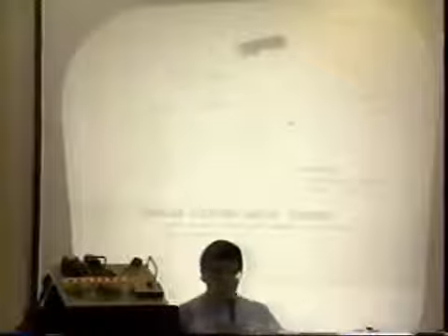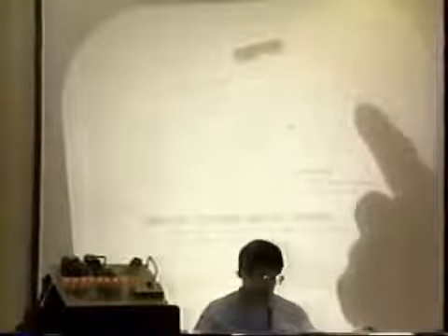Now, why stepping motor? You see, when I give it those commands, 0123, 0123, I know where the motor is. Your printer knows where it is every time it advances the paper. That's because it's a stepping motor that advances it, and it goes so many steps. The thing that goes back and forth is a stepping motor, and it knows where it is. It goes back and forth because it's going a special increment. And just to make sure, they put a little LED or something at the end to know when it reaches a limit, and they send that information back to the computer to tell it where to start. But basically, it runs without any feedback. That's why they're so neat.